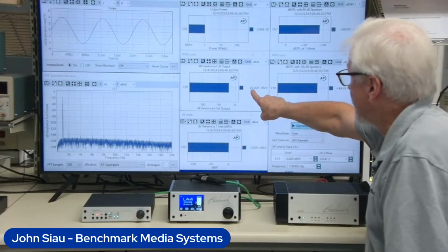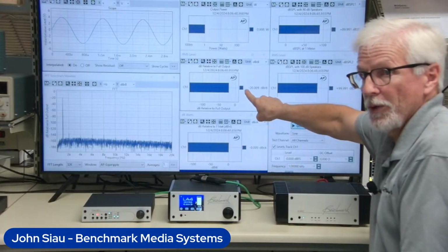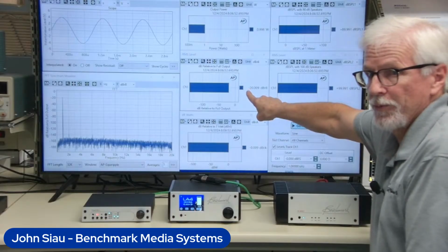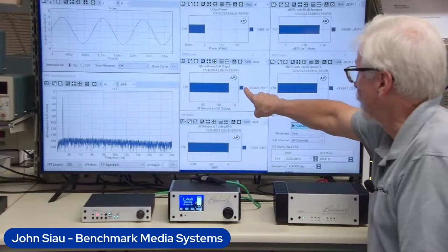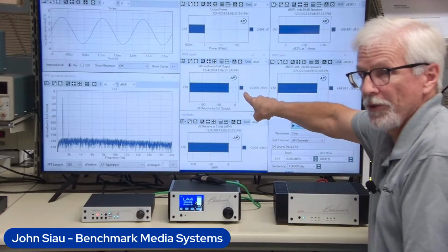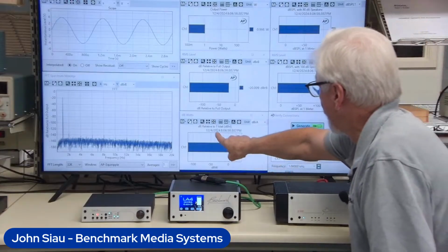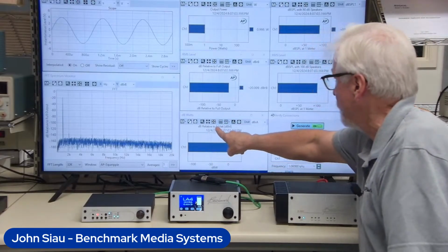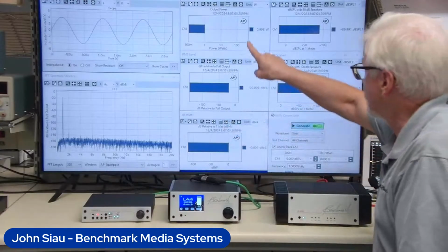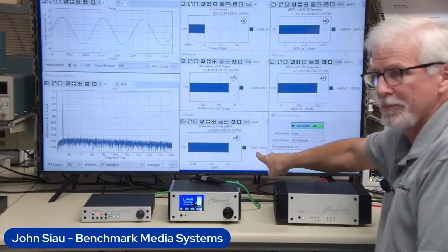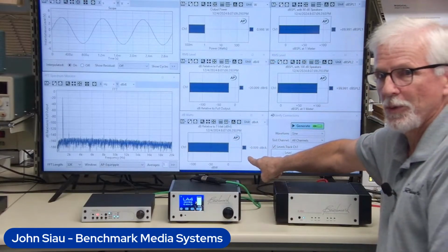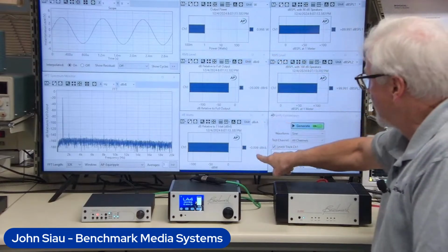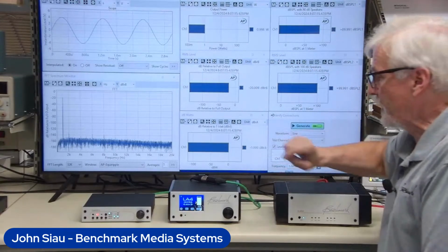That's exactly 20 dB below the maximum output of the amplifier at its rated 100 watt output. So I'm running right now 20 dB below full output. This meter down here is dB relative to 1 watt. Because I'm at 1 watt, I'm 0 dB relative to 1 watt. If I was putting out 100 watts, I'd be at 20 dB watts.